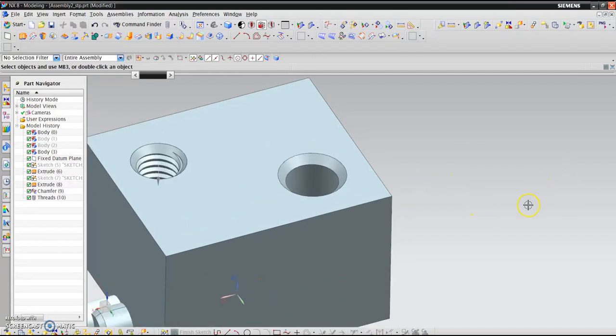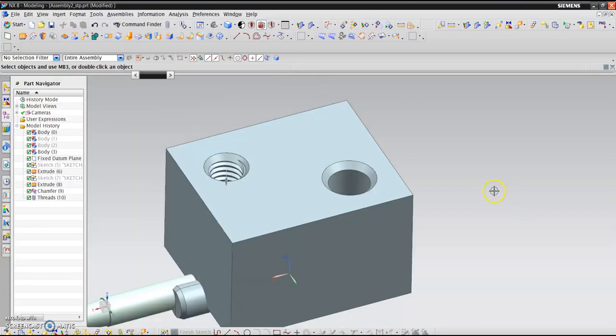Depending on the application, if they want really good threads, the thread percentage will be specified on the drawings. The thread percentage starts from 60% thread or 75% thread. Obviously, the higher the percentage of threads, the more they change the core size, the drill size used before the tapping application.